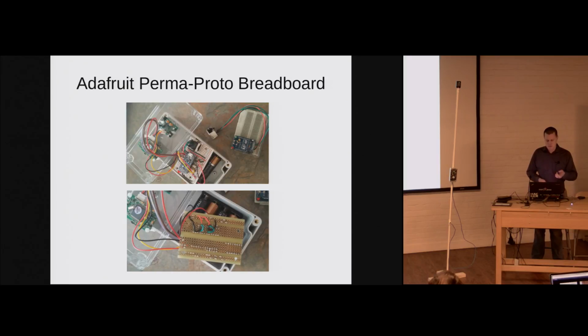So these jumper pins, like I said, they're hardware feature toggles, so when you move them from a low voltage to a high voltage and then reboot the board, it'll load another program within the Arduino and basically set it up so you can tune in your motion detector. The other one will receive ping packets from this transmitter, and when it receives a message, it just lights up the LED, so you can visually see that, okay, I know that this transmitter is talking to the receiver board, and I have that line of sight without having to take a laptop out with you and look at logs and that sort of thing.